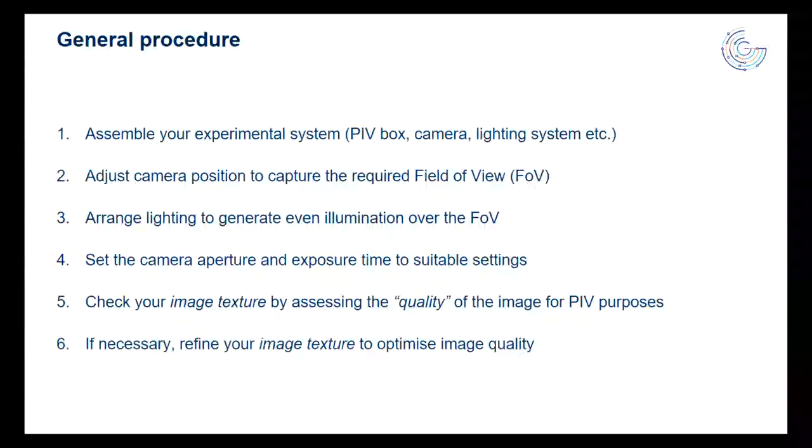So as I said at the end here, if necessary, refine your image texture to optimize image quality. And what you'll tend to find is you might do this once for one experiment, and from that you'll get a good feel about how the makeup of your soil is going to influence the output image texture quality. You'll get a feel for how much seeding you need, and next time you can probably short circuit the process and go straight to the right answer by experience. But I think the first time it's important to do it rigorously, and I'll show you a technique for doing that later on.